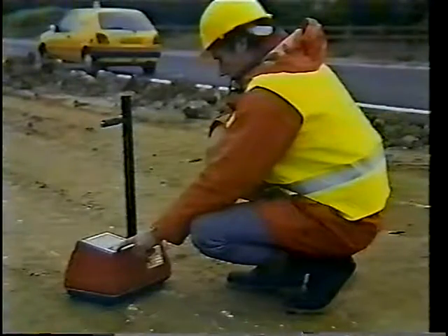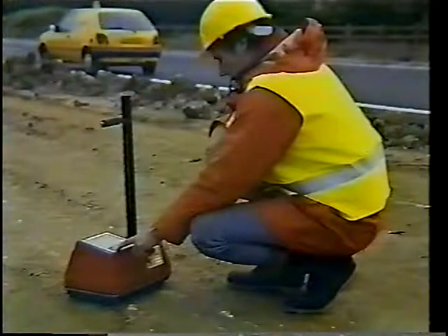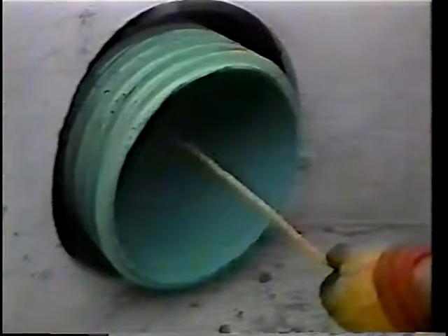Pipe and joints must be inspected, the placement of the backfill monitored, and compaction levels checked at every stage of construction. Once installed, the pipe must be inspected and tested before the line is accepted. First, the interior may need cleaning to remove dirt and debris. The pipe can then be inspected with a lamp, video camera, or go/no-go mandrel for any local excess deformation or deflection.